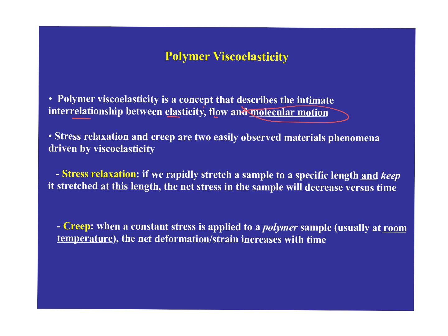And this is also important from the standpoint of flow, because of course, as you'll recall, we're asking these polymer melts to move down these tiny little channels and go into these tiny little gates and fill some kind of three-dimensional feature. And so those small passageways give rise, as you'll see, to plenty of opportunities for viscosity to build up and create what's called short shots, which means that instead of the 100% of what you want, you get 98% or 95%, and parts are missing.